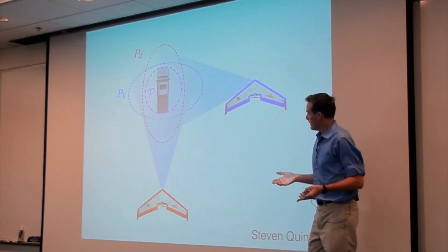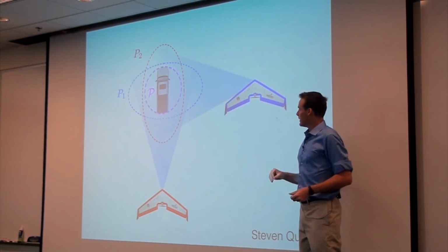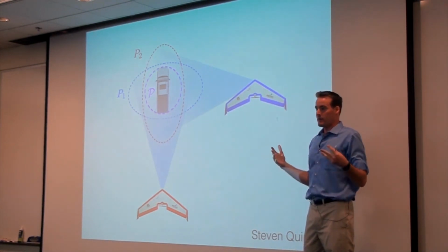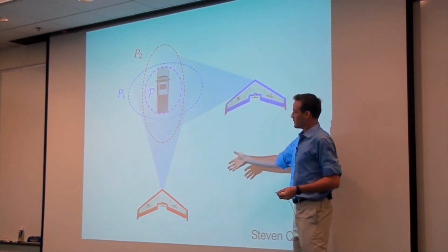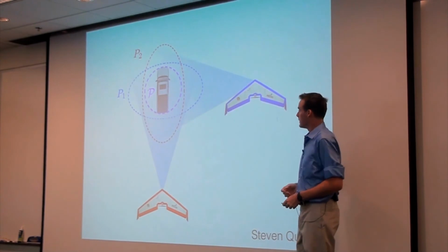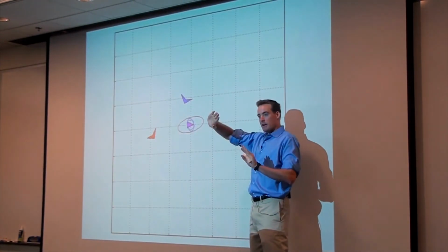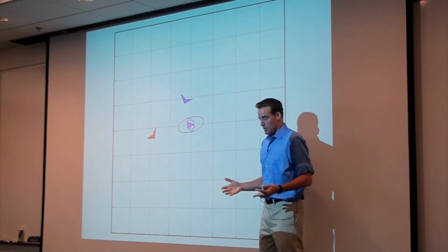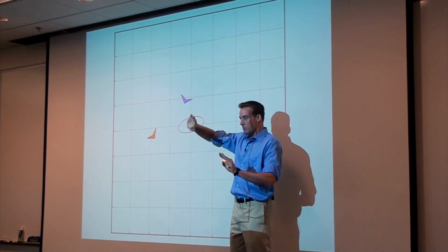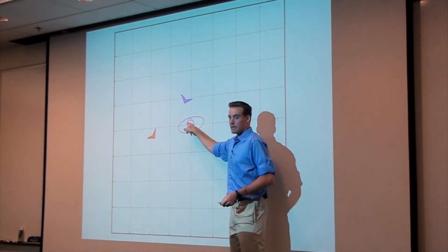The problem with that is that the UAVs cannot magically track at 90 degrees, and follow this truck wherever it goes. These are called non-holonomic vehicles. They can't just move however they want. They're subject to certain flight constraints. And so what Stephen did was, instead of trying to keep them at 90 degrees, he arranged an optimization problem where the goal is not to keep them at 90 degrees, but to minimize the size of this combined uncertainty ellipse, of this pink ellipse here.